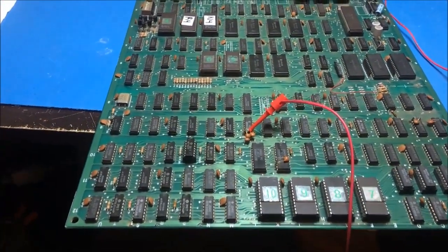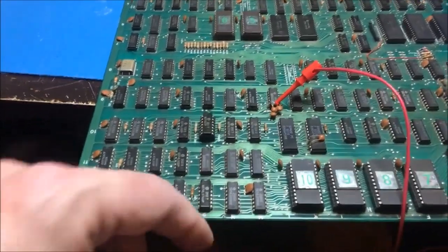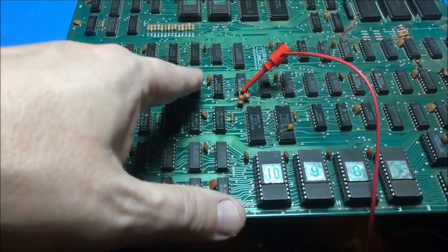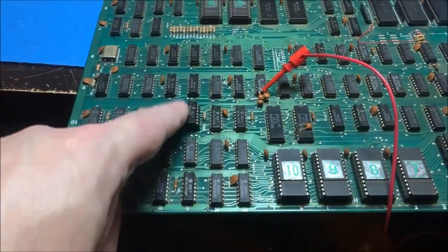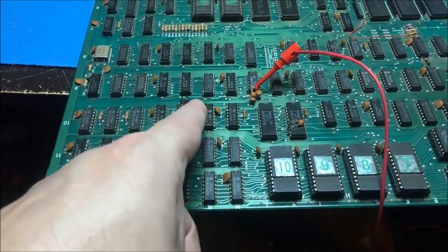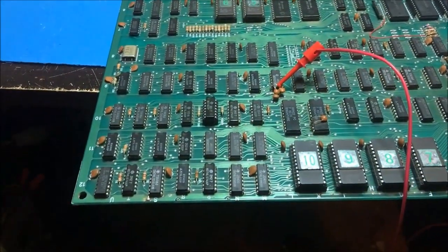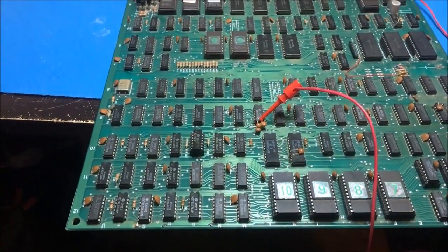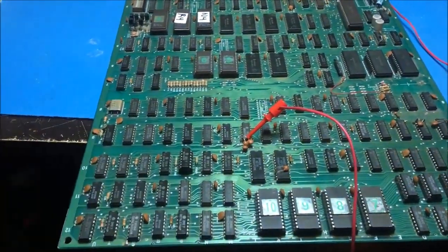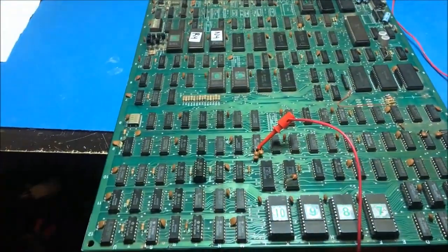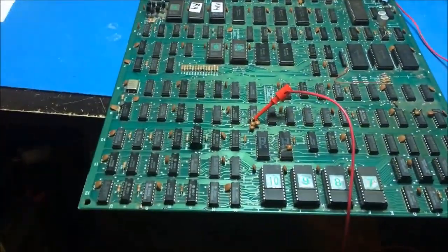So I had gone ahead and did some sync mod that I found online, and it was piggybacking a chip here, piggybacking a chip here, and just a bunch of jumper wires. One jumper wire to this guy right here. One of these legs was out of the socket and pulled out. Well, I just went ahead and hooked the board up with that mod all on it. And it came up kind of goofy. It was not really synced right.